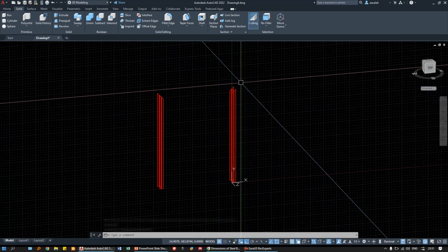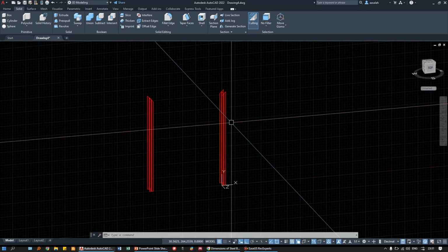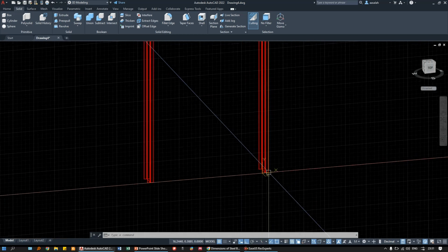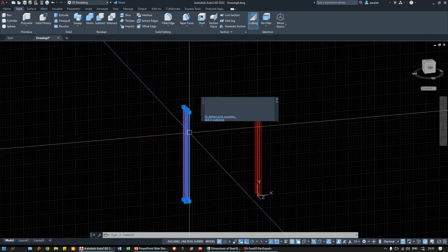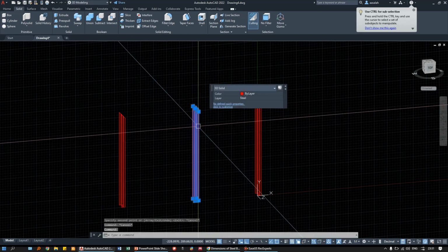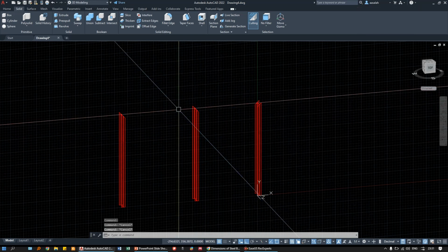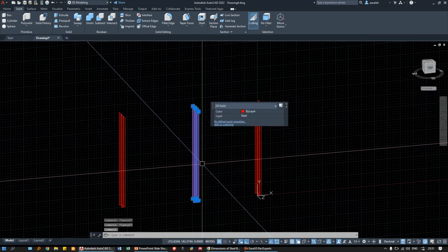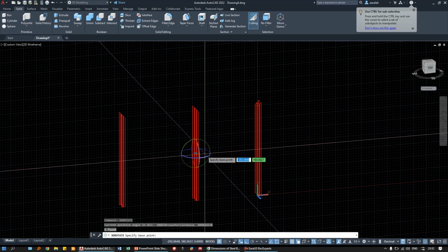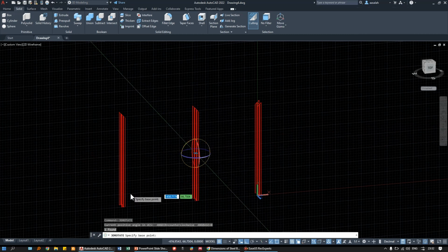So now if I want to connect these 2 beams to form a frame, I'm going to do another cut at the end. So let's select this beam, make it this side, and select this beam. I want to rotate this beam horizontally so it can connect this head to this head. So I'm going to select it again, and then 3D rotation. When I select one of these circles, it will rotate the beam the way I want. So I'm going to select the green circle.